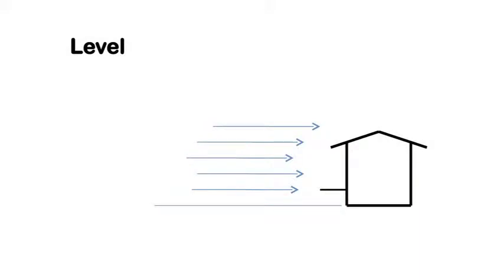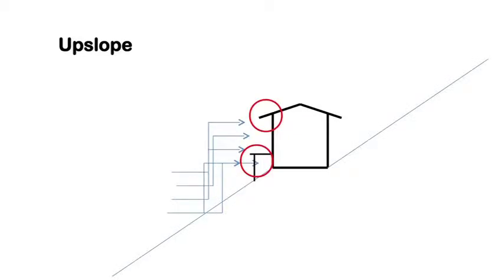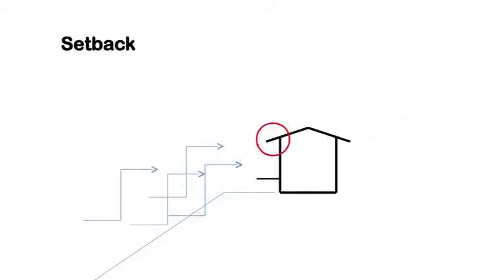If you are on a slope without any setback, and the fire can come up the hill at you, you have overhanging deck, big eave, then you need to think about these particular components in particular, because they may need special treatment if you want to reinforce your house part, given how your house is set on the property.